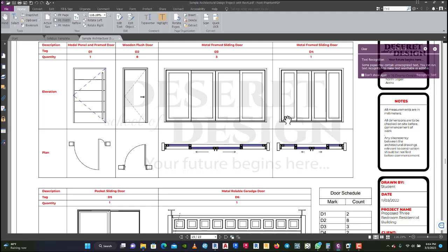Sometimes people do it on the drawing, but forgetting that normally the door comes with framing. So if on the drawing you say door 900, the opening is 900. Now that door is not exactly 900. So if the mason or whoever is on there leaves 900, now when they come and fix the framing before the door comes, you no more get 900 door. You have to now come and plane because framing will take its place. But when you do it this way and put in a natural dimension, you might know the exact opening you have to leave, including the framing.